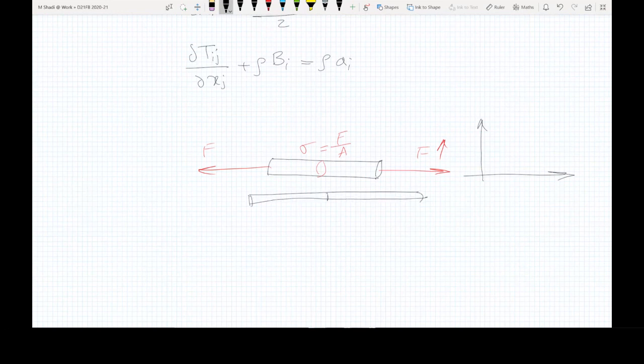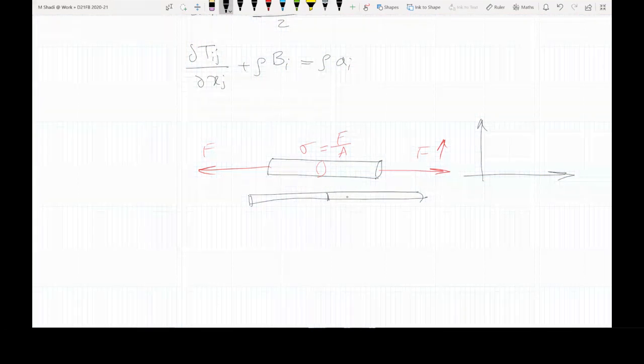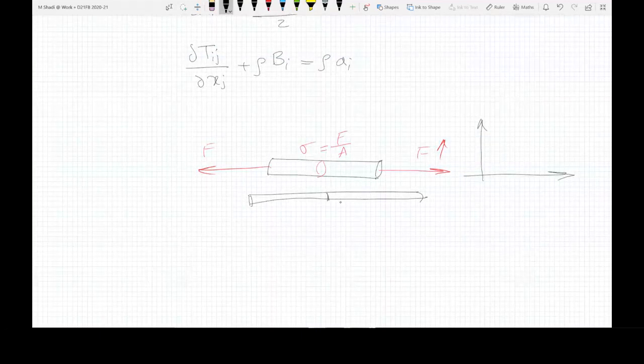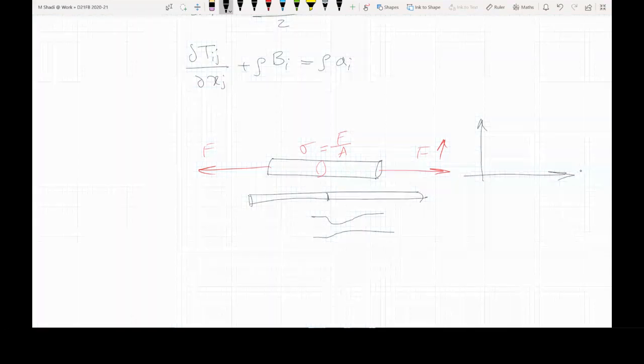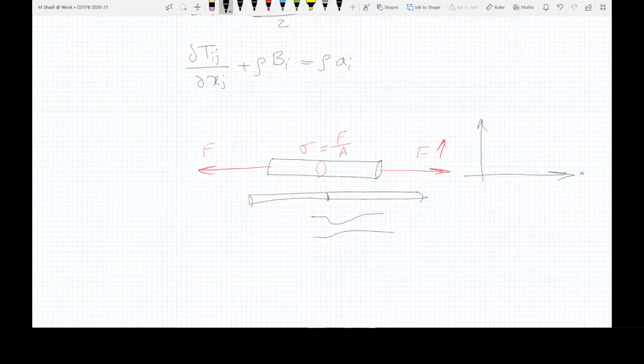At some section, usually close to the middle, it is going to become quite thin and is going to break. So if you look into the relation between the strain and the stress, you'll see that this is going to increase in a relatively linear way, and then it is going to yield, and then it is going to expand quite quickly.